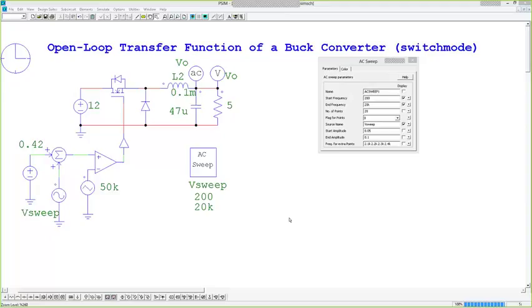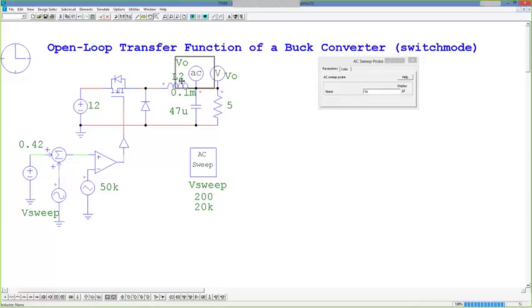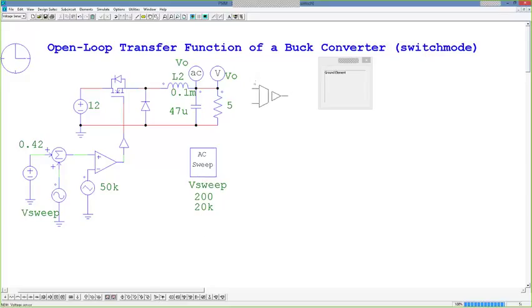The next thing you need to look at, so that's running an AC sweep. The AC sweep probe is ground referenced. It's important to note, it's always referenced to ground. If you want to reference on something like a flyback, you should use the isolated voltage sensor, and put the probe on the other end here, because this will then give you an output relative to ground.